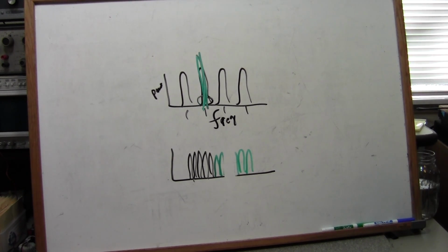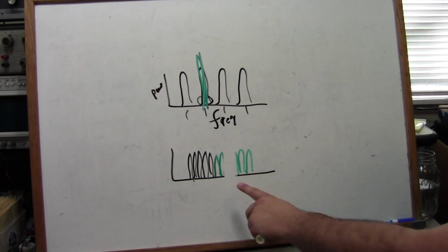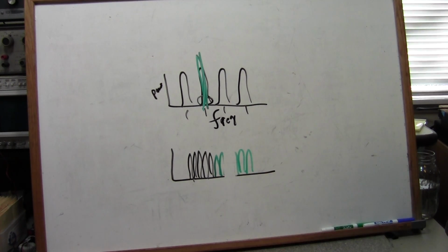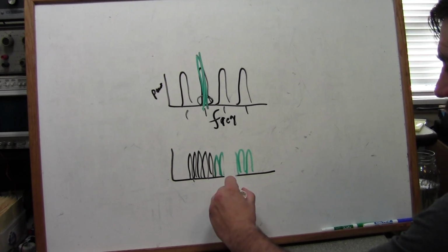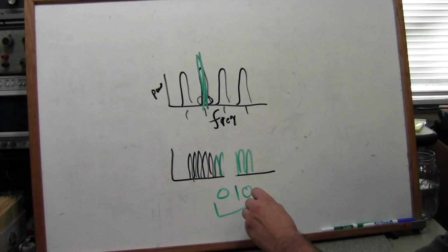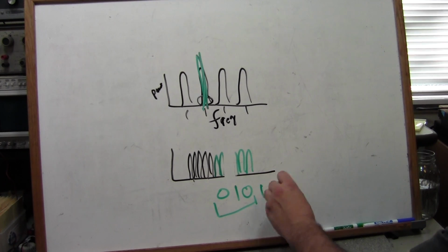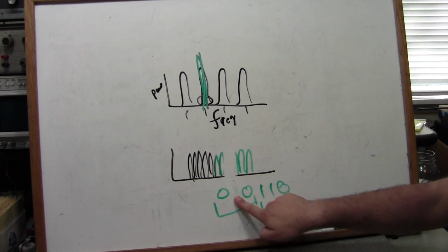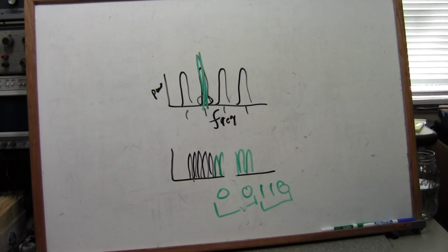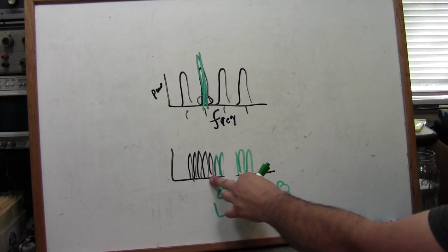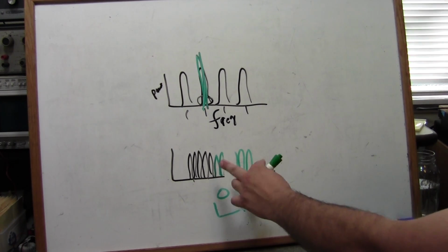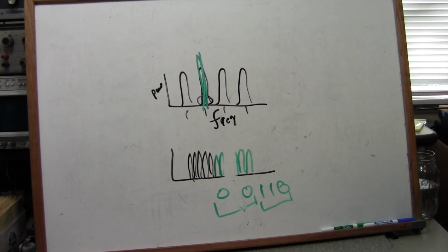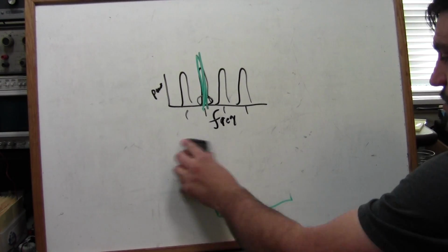Of course, if you didn't have any error correcting codes, you would lose 10% or 5% or 20% of your data if you lose one of your carriers. But by taking a smaller number and spreading it out so that you have additional bits that you can then reinterpret the ones that you lose with, which is called forward error correcting, you can actually continue to operate at a reduced rate or reduced quality with the selective fading. The selective fading is a very big deal.